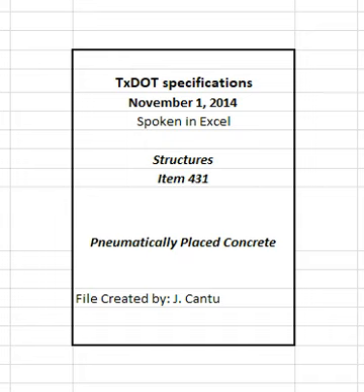Provide joints, side forms, headers, and shooting strips for backing or paneling. Use ground or gauging wires where necessary to establish thickness, surface planes, and finish lines.